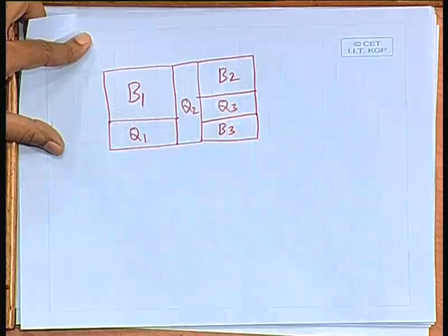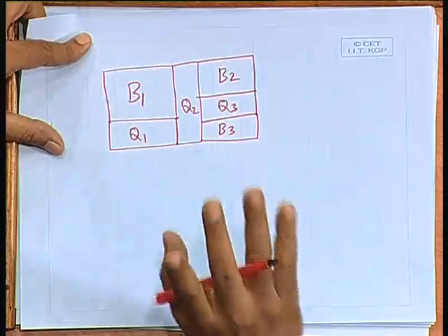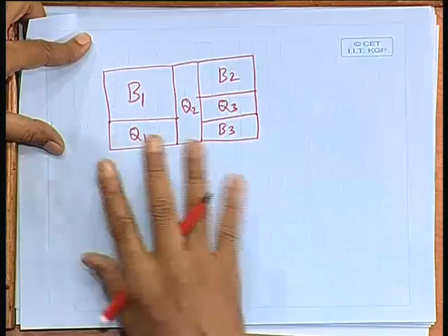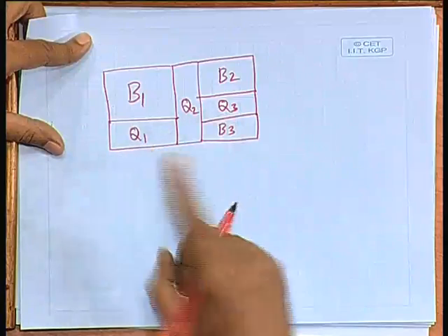Because we have all these automated tools, how do we know how it will divide this? See, this we shall come to a little later when we go into the problem of global routing, because this concept is not really required in placement. This is just a notation we are introducing now, but exactly how these regions are defined, that we will see in detail later when we talk about global routing. Okay. Given the overall placement, how do you define these rectangular regions? The next subproblem is that for each net, which is the sequence of regions that need to be traversed. Okay, so this problem will be coming to later.